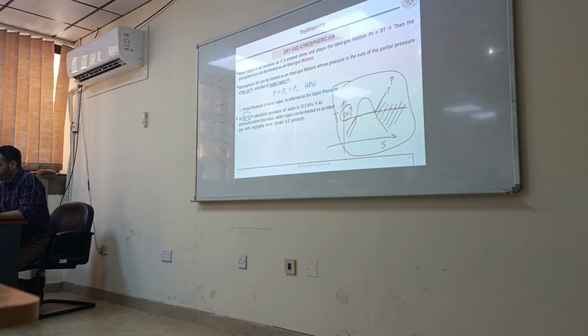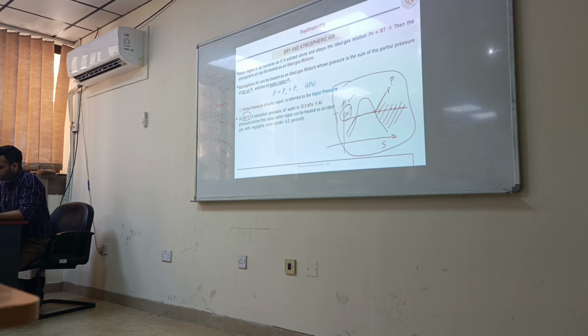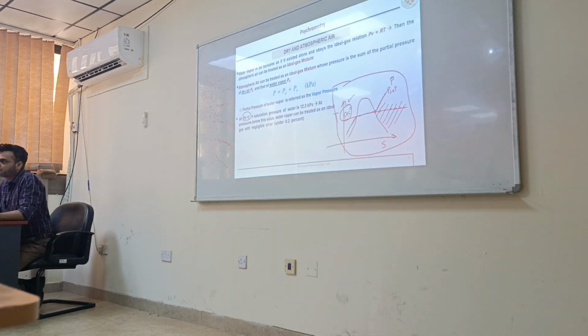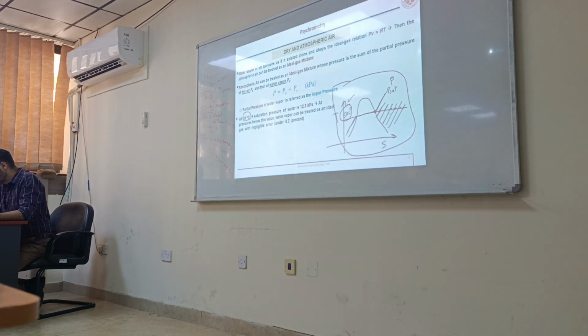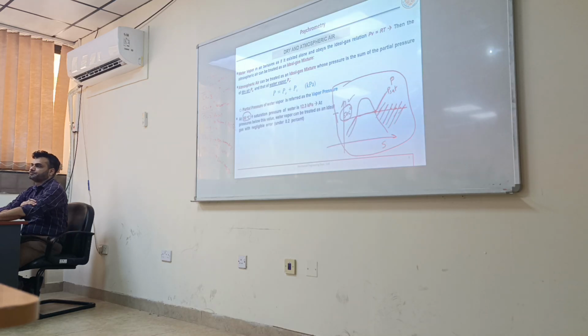Water is vapor at 50 degrees Celsius. Why? Because what is this pressure? The saturation pressure corresponding to 50. So all these pressures are lower than P sat, right?